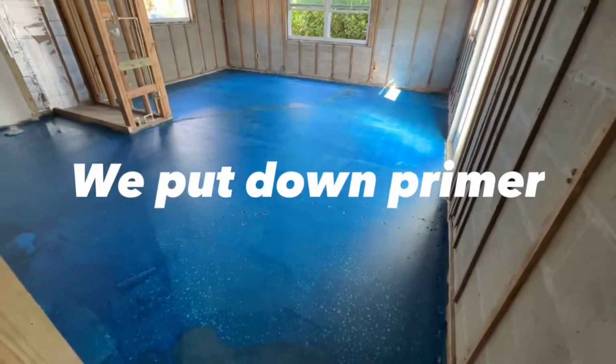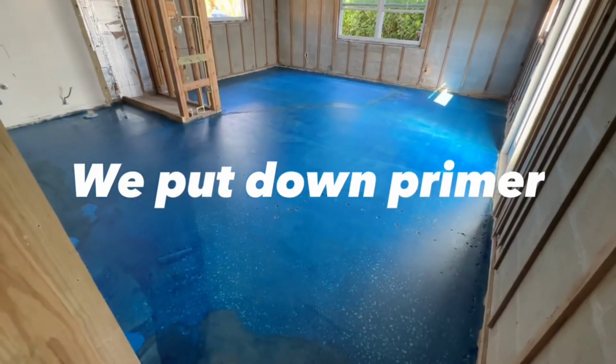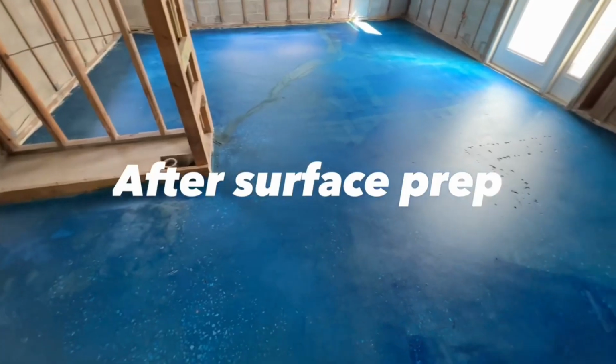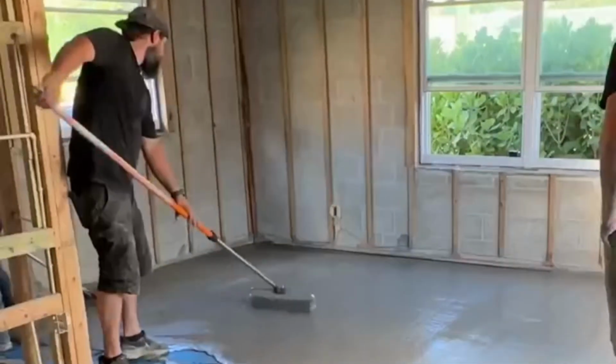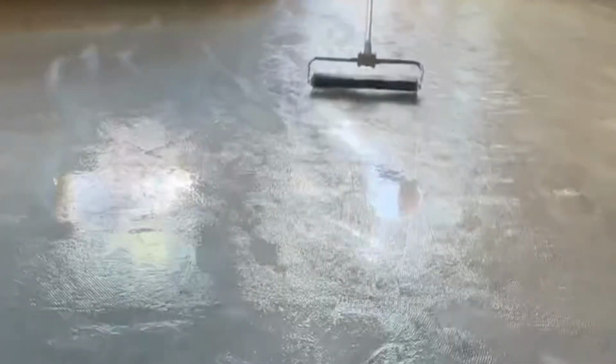You can also apply a compatible primer to the concrete surface. The primer helps seal the surface and creates a thin film air block, reducing the chances of outgassing. And if you're installing a self-leveling overlay, you can use a spike roller to release any trapped air.